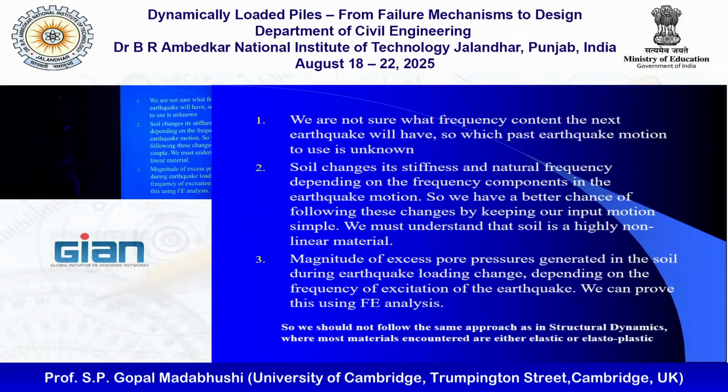So there's no chance of telling you what the frequency content is. Basically, future earthquakes are always going to have some unknown frequency content. Amplitude, maybe we can guess, but not the frequency content. So is it not better, because we don't know the frequency anyhow, to use sinusoidal motions? That seems a reasonable argument. Also, since this whole course is about failure mechanisms and how we understand them and use them for design, if you do sinusoidal motions, it's so much easier to identify the failure mechanisms. I'll show you some examples in the lecture after tea.